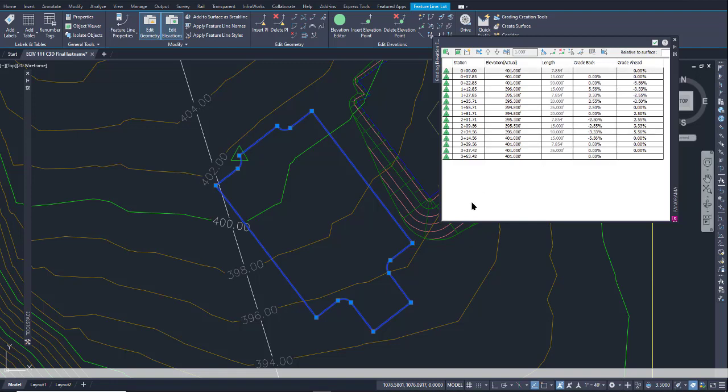All right, now that I've entered those, you can see all these elevations. And if you look at the percentage on my slopes, and these are between the points, they're all relatively minor. They're not huge. And they all have at least a 2% slope.